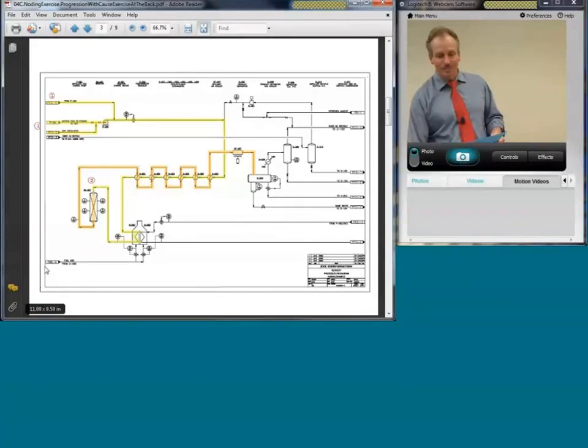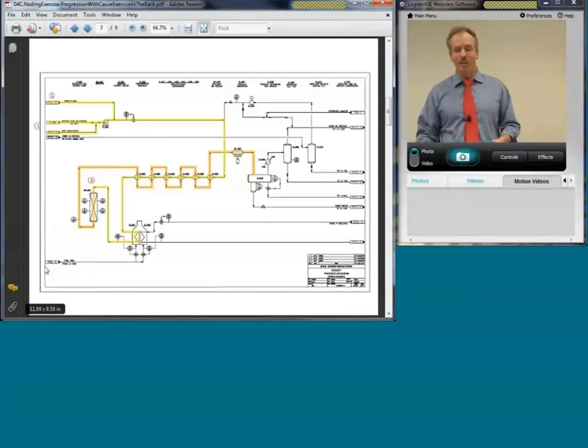That's the main flow of the process. After that, I would take it from the product separator and really look at that. The team's really familiar with the feed coming into the unit, picking up heat and going into the reactor, coming out, releasing its heat, going through the fin fan cooler and also the product separator, and that's where I would put the third node, and that's what you're seeing in pink.